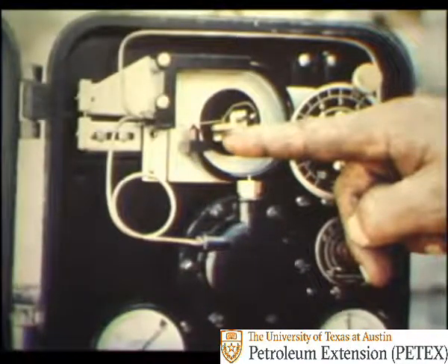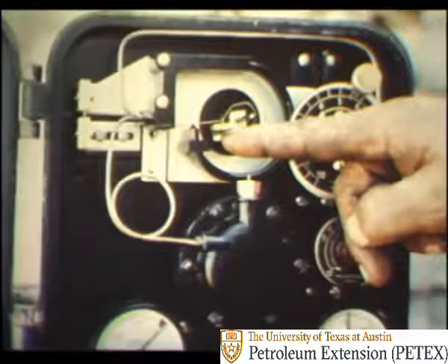The other feature of a controller you'll need to be familiar with for troubleshooting is the flapper, which covers the nozzle. The flapper and nozzle control the output air signal pressure to operate the control valve. The control valve may be operated or stroked by carefully holding the flapper on the nozzle or by lifting it off with your finger. Handle the flapper carefully to prevent bending or distorting the flapper or linkage. By using the flapper to stroke the control valve, you will not upset the control point, and the level or pressure should return to the preset point without changing the adjustment knob.